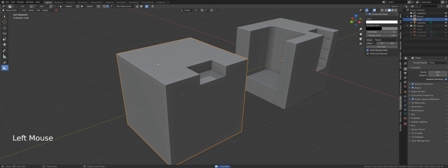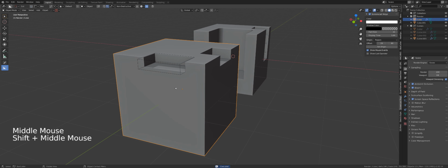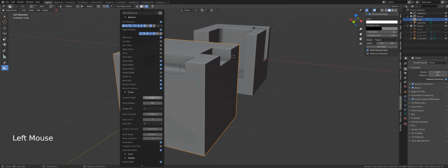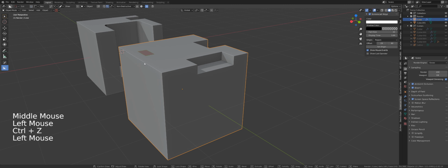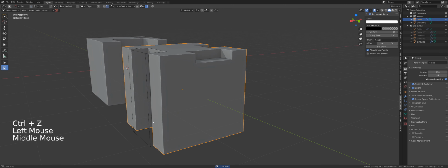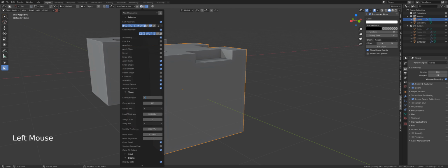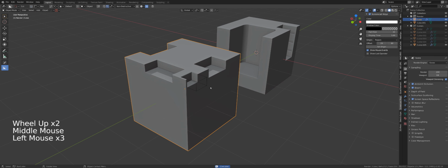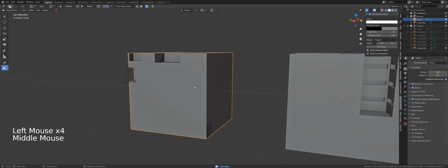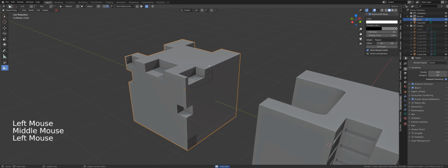Now if I select this cube and draw a shape and click to perform a laser cut, remember from the previous parts, the laser cut used to go through the entire mesh, but that was because the depth was set to 0. So if I revert it back to 0, it's going to go through the entire depth of the mesh. However, if I switch it back to 0.2 or whatever you want, every time you perform a laser cut, it doesn't matter from which direction, it's going to be the same depth.